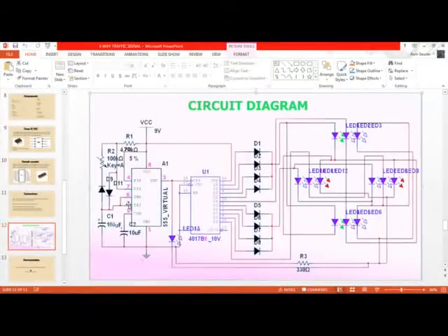You can make it open, you don't have to use the diode here. You can open this port and you can short this. And here, as you can see, I told before that threshold and trigger will be shorted. As you can see, 6 and 2 are shorted, and they are connected to the variable resistor. See that?